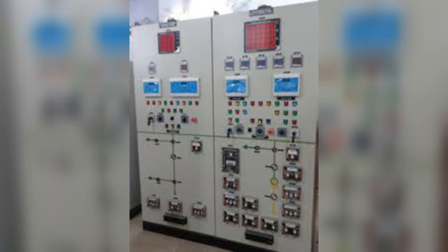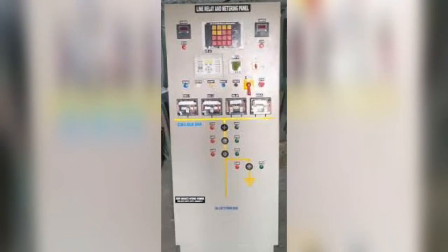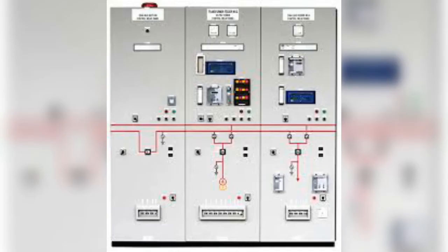What are the causes of generator under voltage? What are the causes of generator under frequency or under voltage? Low voltage in a diesel generator set is one of the common faults. The unstable speed of an engine causes the unstable voltage of a generator set. Poor circulation in the fuel pipe of a genset causes unstable engine speed, which causes voltage instability.